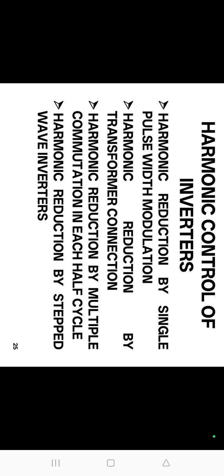With this method of harmonic reduction, the inverter is derated by 16.1%. Another disadvantage of this method is that there are additional 4 commutations per cycle, and this leads to more switching losses, which decrease the efficiency of the operation.